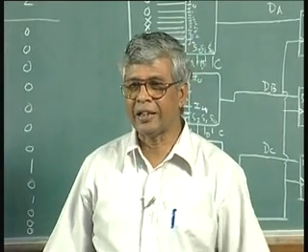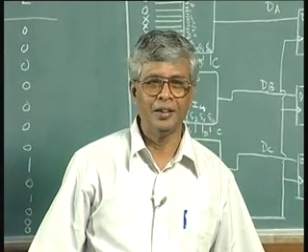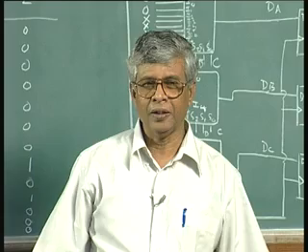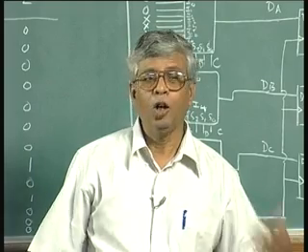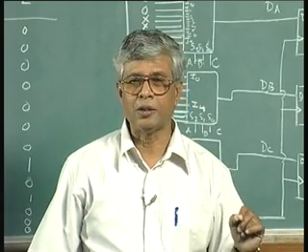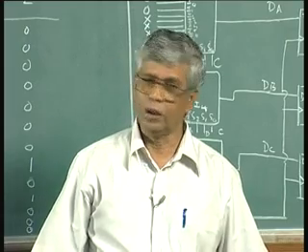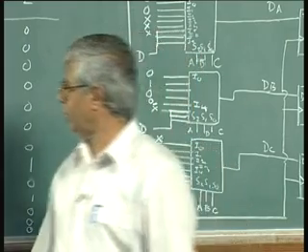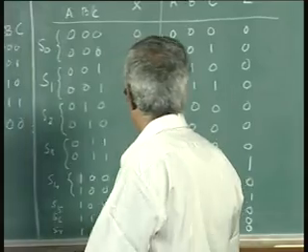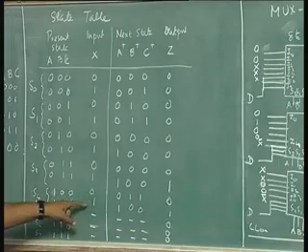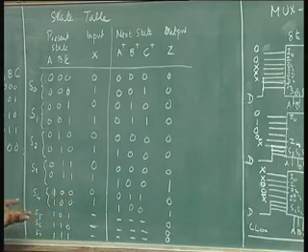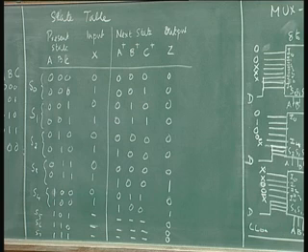so we have finished this implementation, and then the output has not been completed. For the output, again you can draw a Karnaugh map, you know. You can do that if you want to. You can draw a Karnaugh map because there are only how many entries of 1? There are only 1, 2, 3, 4 entries of 1. The rest are 0. I can draw a Karnaugh map and make a simple gate circuit, but if you want to use any multiplexer, it is fine. I can give you a multiplexer based output also.